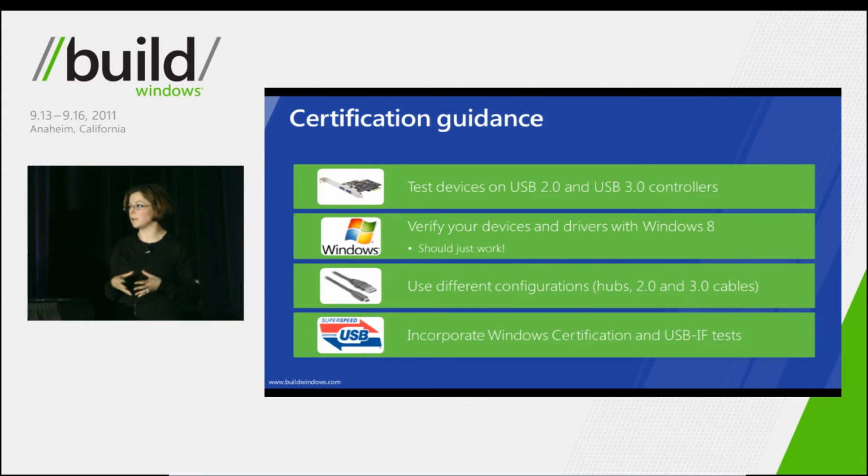Another thing to keep in mind is the configurations, how users plug in their devices. Many enthusiast users and developers use hubs, USB hubs. I personally only found out about USB hubs when I started on the USB team 2 years ago. But one of the key things is they make connecting and moving devices very, very easy. Apparently they're quite common. And so it is important to test your device behind a hub because the device might work very differently when you're adding another layer in the middle.